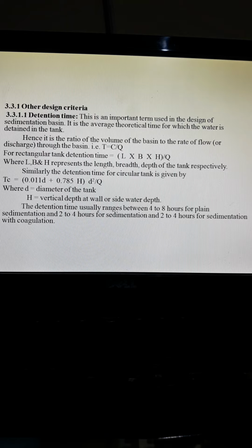And then at the farther end, about an equal amount of space is provided for withdrawal of the water without creating any turbulence. That is called the outlet zone. And at the bottom of the tank we provide sufficient space for sludge accumulation. That zone is called the sludge zone. The space between the inlet zone and outlet zone, above the sludge zone, is called the settling zone.